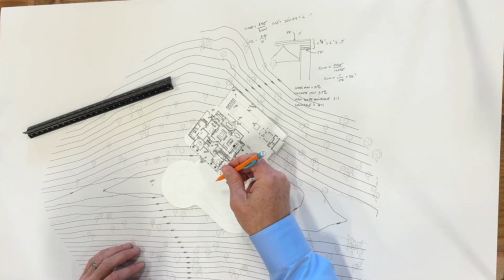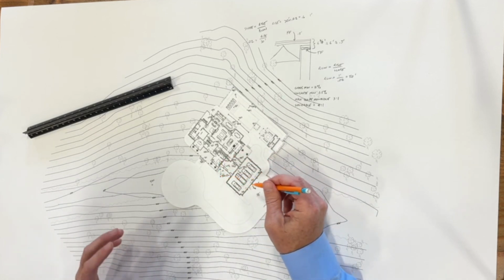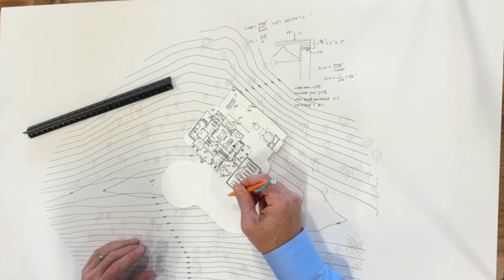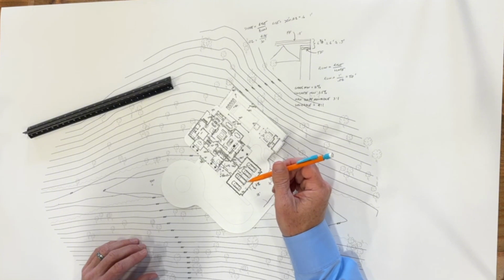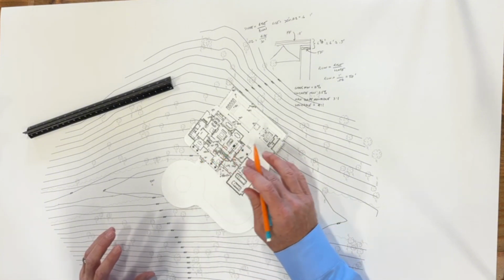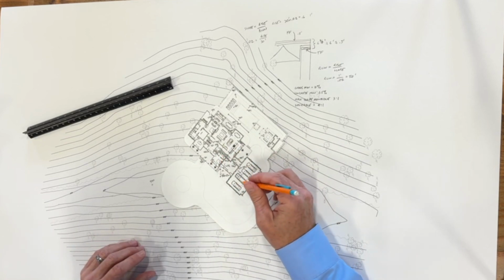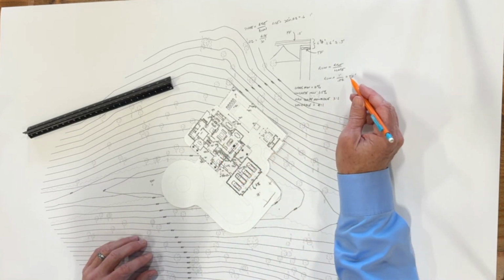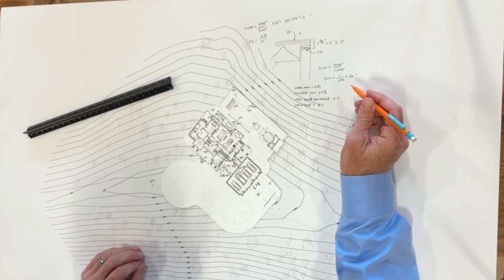Okay, now on the front of the house, you got the same thing. You come out this 33 feet and you have a nice flat, but I don't know, that almost seems like a little too much to me. It's going to be like too flat right there. So let's go say 4% on that. So Christian, what's that? Is 4%, must be 25 feet.